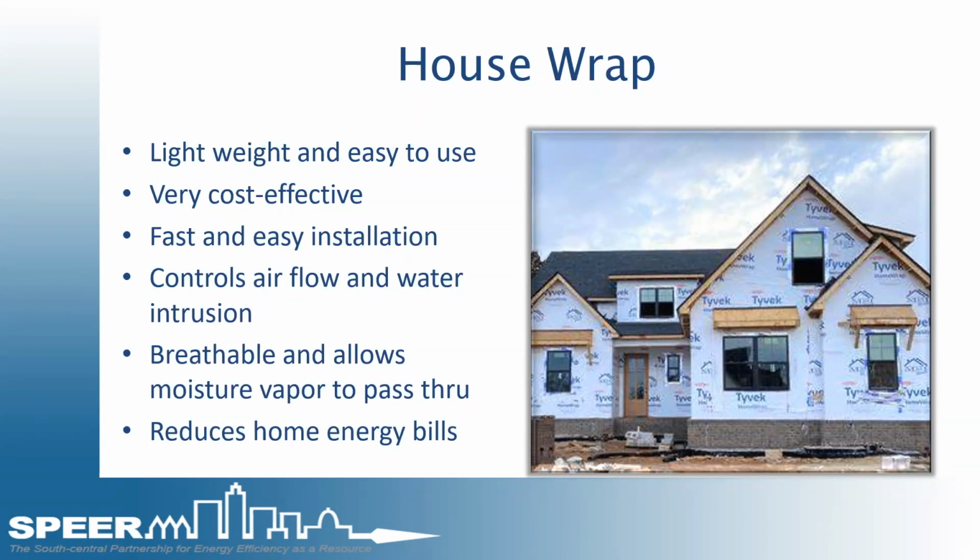But again, it goes back to if it's done correctly. If it's cut and patched multiple times, you have to make sure those seams are sealed. If they're not, that's going to allow for air and more bulk water to pull through. So overlapping these correctly, creating that drainage plane, and doing it correctly so that bulk water can escape, but it actually seals up that member.